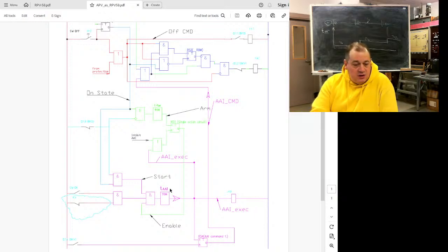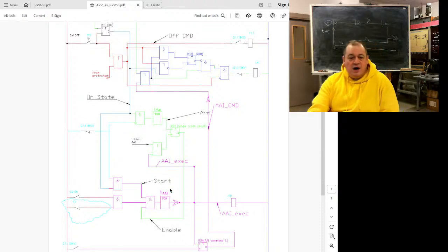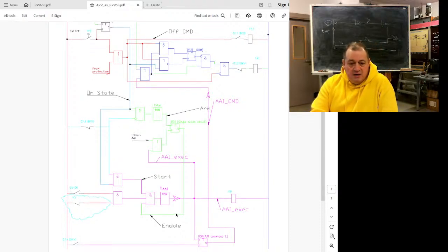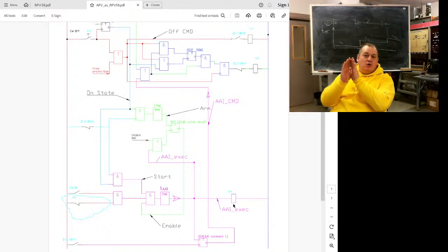This on-timer performs the auto reclosing delay. After the reclosing delay, what happens? Signal is sent to do auto reclosing. This one is a special relay. We did send the reclosing command. It's a nice indicator. We had auto reclosing.